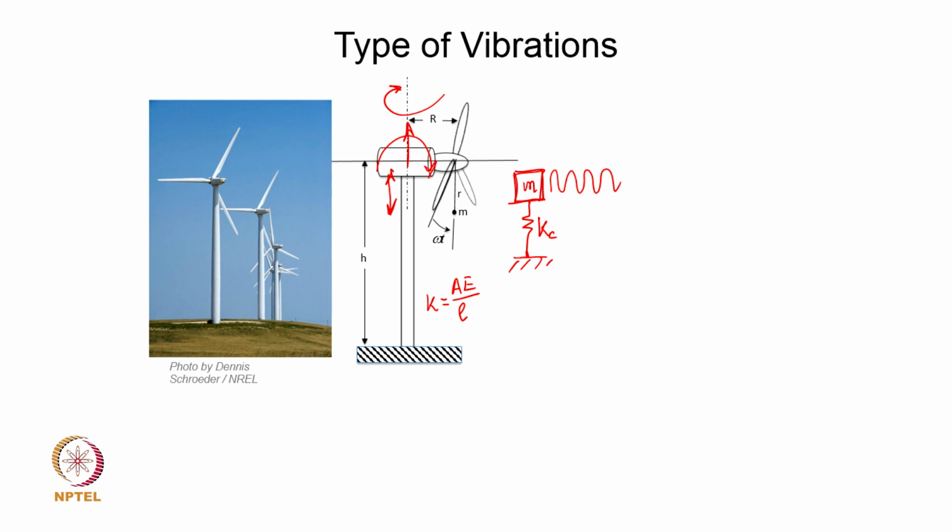But if you treat the same system as a bending vibration case, there is a mass sitting at the tip of this beam, and if this is vibrating laterally, which is quite possible given the way the rotor rotates and the unbalance located at the radial distance r generates a moment, this is going to have the same mass being used here,